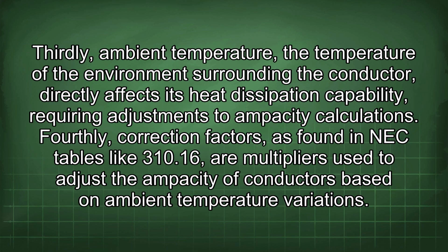Thirdly, ambient temperature, the temperature of the environment surrounding the conductor, directly affects its heat dissipation capability, requiring adjustments to ampacity calculations. Fourthly, correction factors, as found in NEC tables like 310.16, are multipliers used to adjust the ampacity of conductors based on ambient temperature variations.